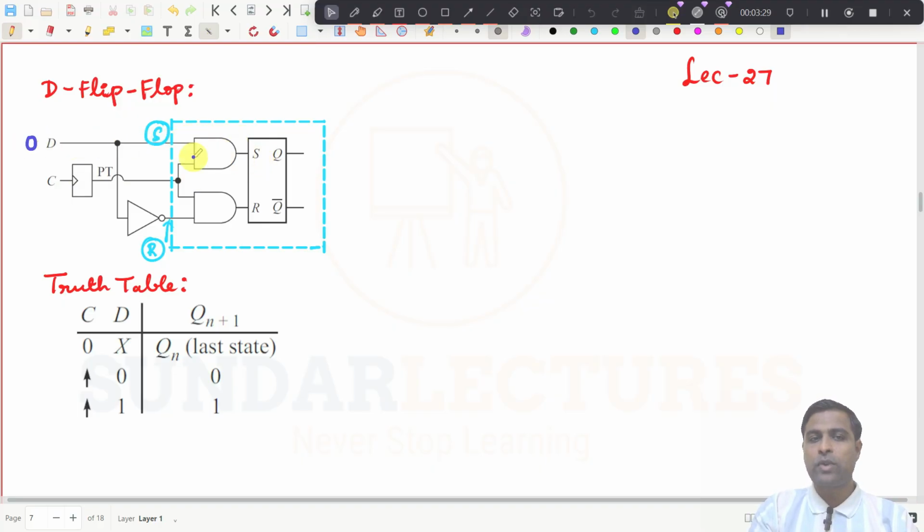This 0 will pass through, because this is an AND gate. If this input is high, then this 0 will pass through. So S will become 0, right? And this 0 is getting 1 here. This one will also go inside because the clock pulse is high. So R is equal to 1.